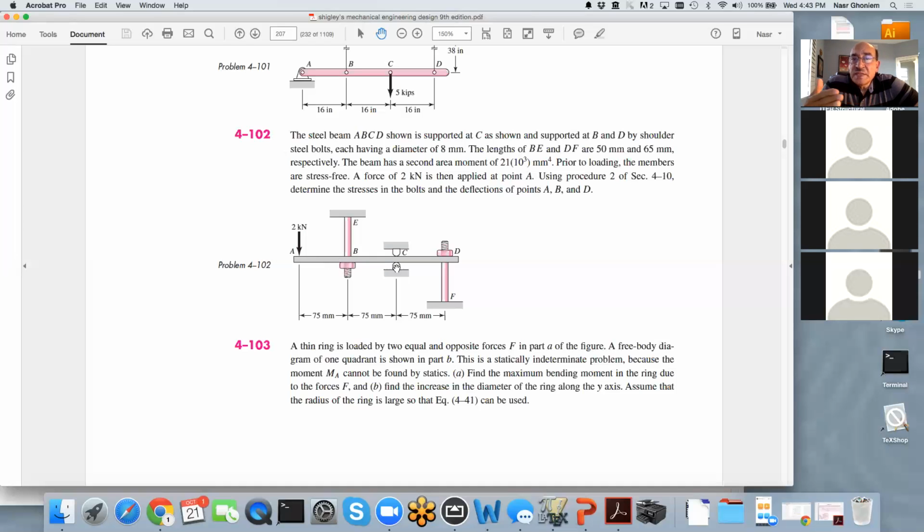I write the moment using singularity functions, including this force, including this force, including this force, including this force. So this is 1, 2, 3. The fourth one, we can ignore it because it's the end of the beam. So basically, I have 1, 2, 3 concentrated forces giving me a moment that I can write an equation with.